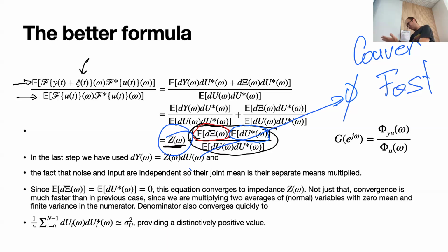This is what I said now. It's rather bizarre. That is why we excite, to increase our signal to noise ratio. But this is the trick that we are doing. Actually, everyone is doing it. Everybody is doing it like this. And regardless of the input, because of this, we can put a broad spectrum input, go through this formula and get the complete impedance over all frequency ranges. The noises just cancel out each other.